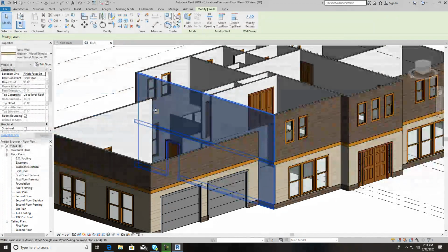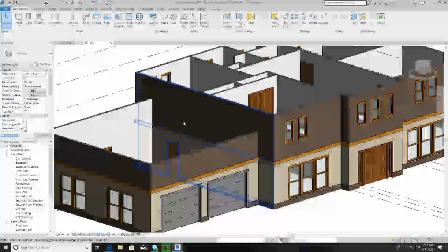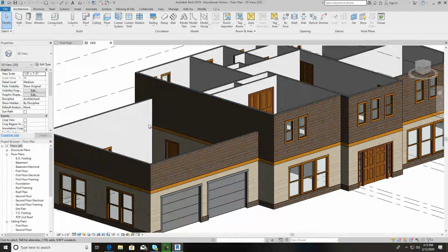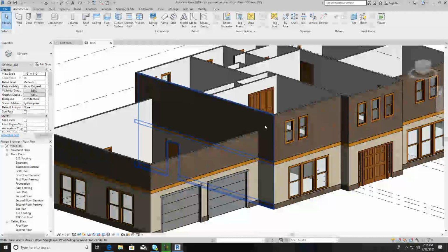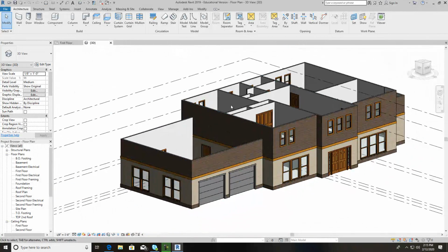That should be a 2 by 6 inside this wall right here, and it should be sheetrock inside of here, okay? Because the majority of this is going to be inside the garage, and then the roof will come up. So you'll only have a section that'll have to have exterior wallboard on it. So let's get in there and fix this real quick.